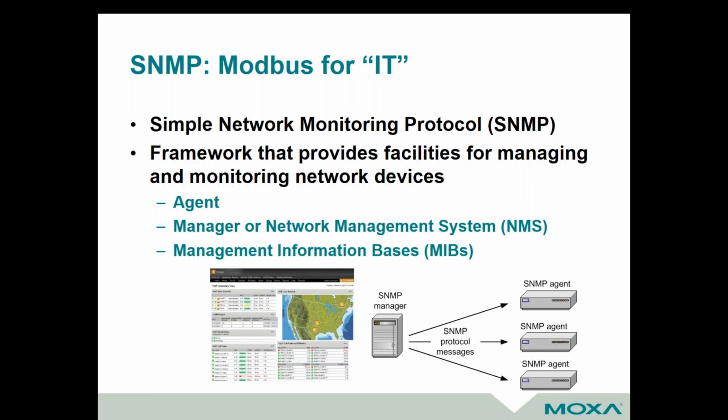And there's a lot of status you can pull from those devices. Those devices need to have something called an agent. If you're on a Windows-based machine like an HMI, you'd need to run an SNMP agent for that. The software running on the server is going to be called a network management system or network monitoring system. And those generally have something like the dashboard over there that you can see, a heat map or a geographic distribution of trouble spots. Really great technology for doing that.